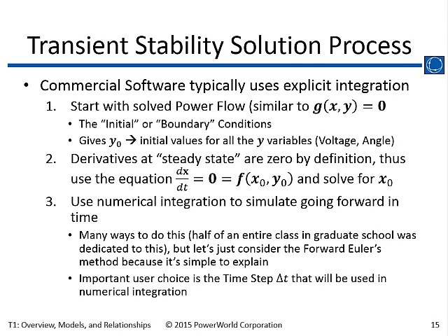So assuming we have a flat solution, or even if we don't, it doesn't matter. You're just going to see initial oscillations if you don't. Then you numerically integrate these differential equations. There are different ways to numerically integrate differential equations. The simplest is a forward Euler method. It's simple to explain, but in PowerWorld we use a little bit more advanced method, which has better numerical stability.